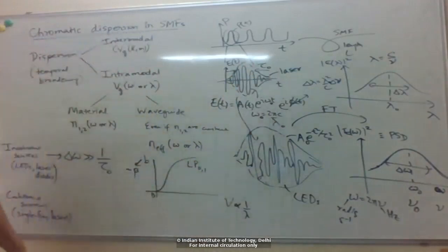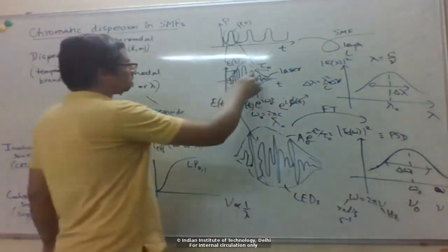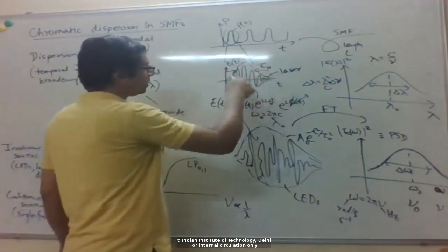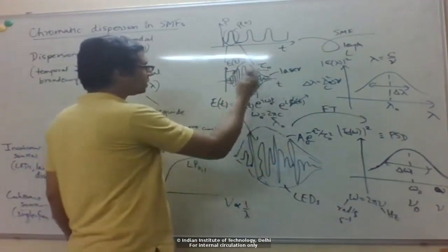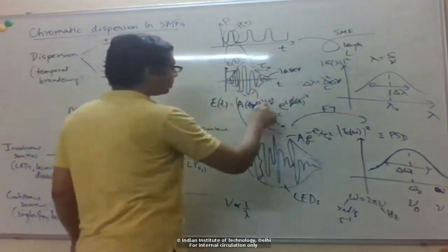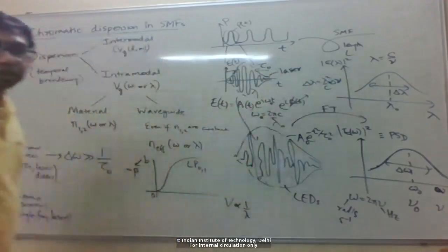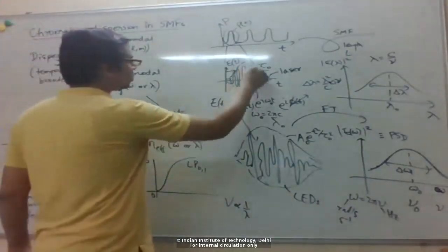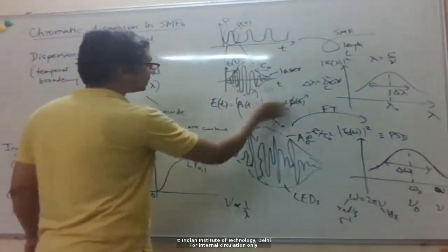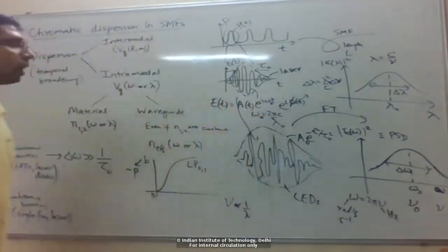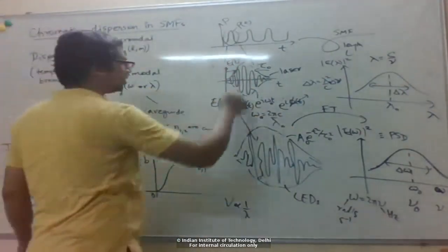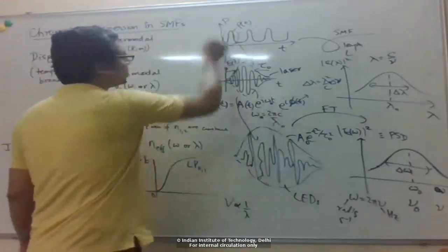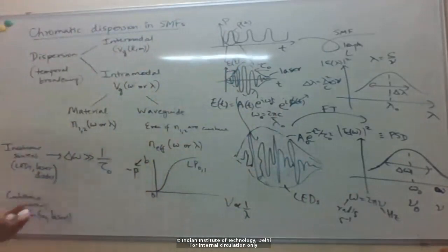So again, you know from your basic Fourier transforms that if you have some signal which you multiply by a carrier, in the spectral domain what that means is that you shift the spectrum to the carrier frequency, right? So basically, what you'll get is the Fourier transform of A of t, but centered at omega naught. Okay, and again the Fourier transform of A of t will just be the inverse of the temporal width, because that's a real thing.